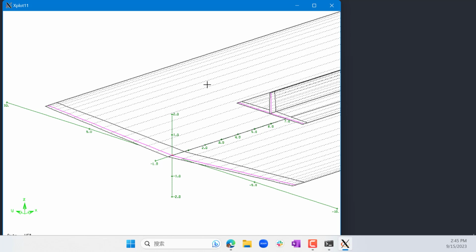And from that angle of attack, you can compute the lift on that section of the wing. And the lift is going to allow you to update the strength of the vortices. Now, after you update the strength of the vortices, the induced flow changes, right? So you have to recompute and change the angle of attack on all the other sections. And you have to re-update the strength of the vortices, etc., etc.